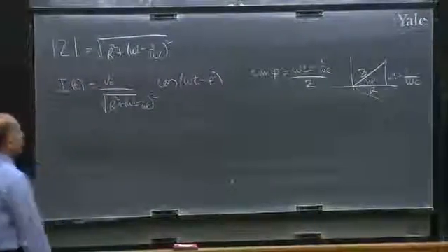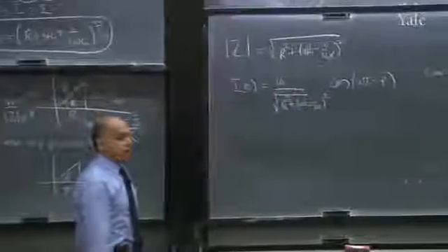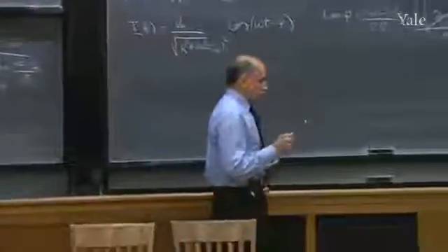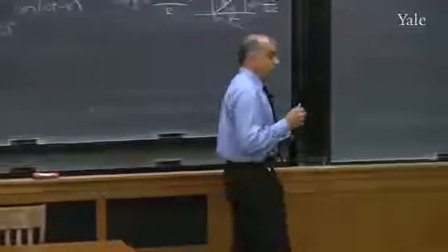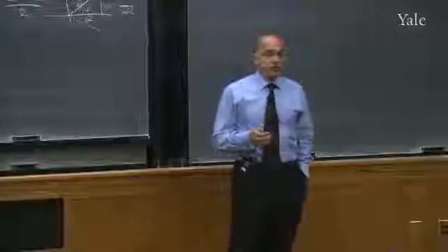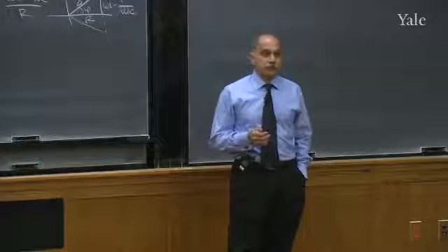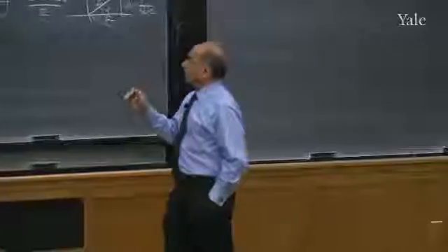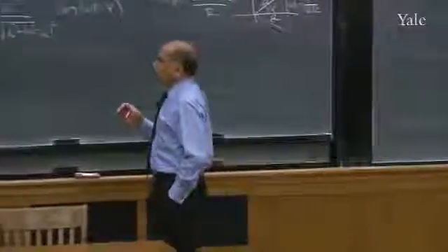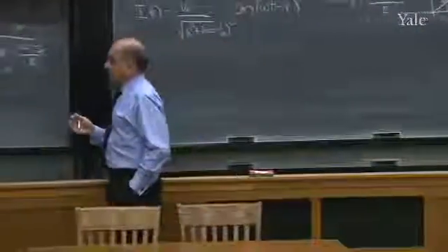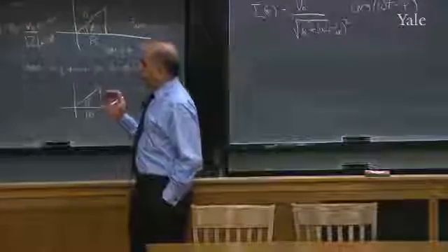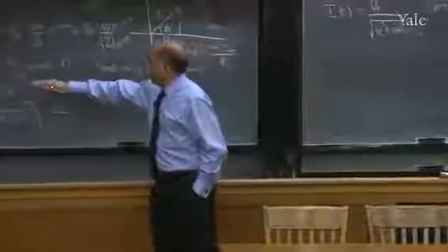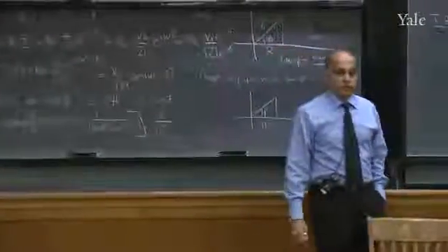So let's look at this answer for one other interesting feature. I want you to know two things. This trick works only if the voltage is a pure oscillatory function like cos omega t. But then you can write it as a real part of e to the i omega t and do this. Secondly, the impedance is not a constant. Whereas the resistance is just 10 ohms, impedance varies with frequency. It's a frequency dependent number that you divide the voltage by to get the current.